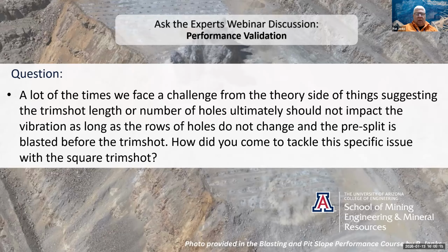However, when it crosses that structure, the behavior changes dramatically, and oftentimes you get significant amplification of the peak particle velocity, and the frequency will fall out of the range of what our frequency target is. So you need to ask those questions. Think about that as you're setting up these shots. Have access to and review that seismograph data so that you can draw some conclusions from it.